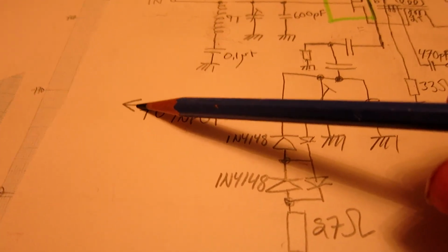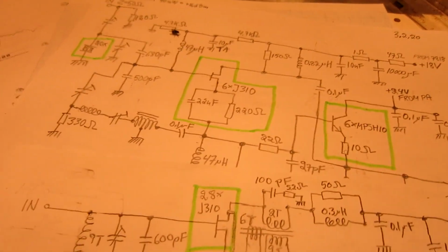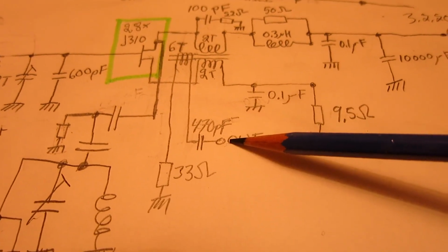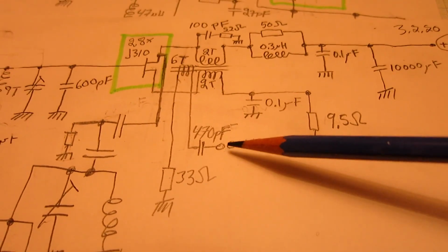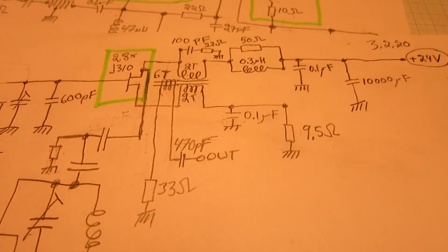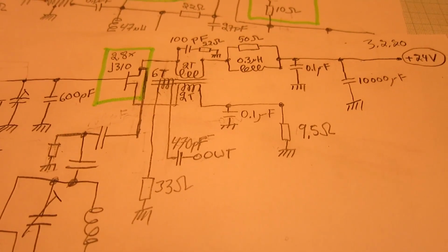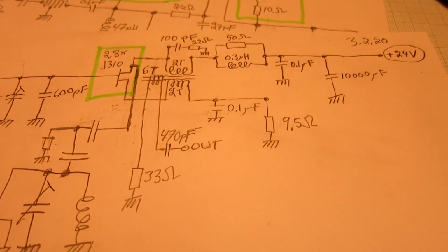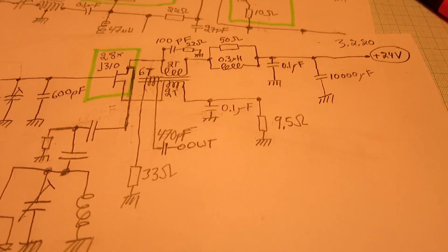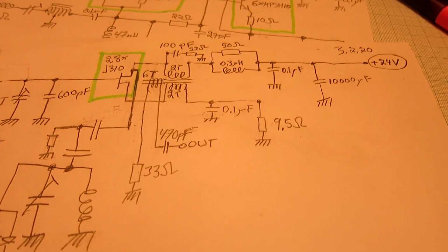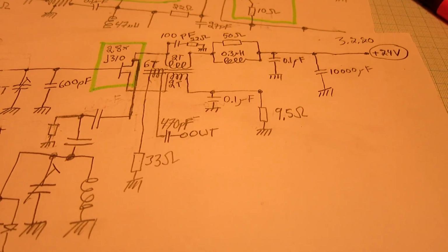But now there is a dummy load here, and I have removed the dummy load I have had on the output here. And instead, on this point, I have put the limiter. First a 6 dB attenuator, then the limiter, and then another 6 dB attenuator to present a reasonable impedance to the signal analyzer, the dual channel receiver.